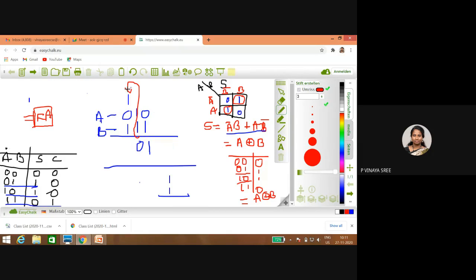When you combine, we have totally 3 bits. If you want to add these 3 bits, first of all the input given for the design should be 3 bits. But how many inputs did we assign for the half adder? Only 2 inputs. If a carry is generated, we are not giving that carry as input. So that's the problem in the half adder.